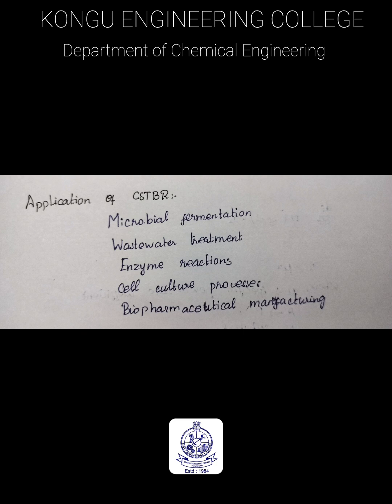Finally, we come to the applications. The applications of CSTBR are industrial production of antibiotics, alcohol and enzymes, wastewater treatment through microbial digestion, continuous fermentation in food industries, for example beer and vinegar, and lastly, cultivation of microbial biomass for single cell protein.